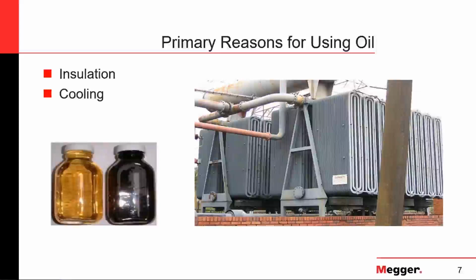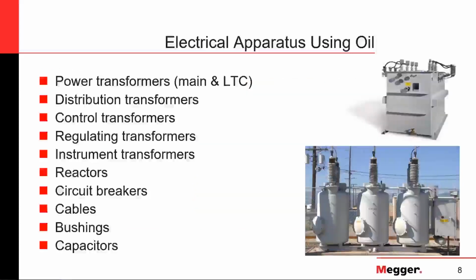Now this solid insulation is rated up to a certain operating temperature, and this operating temperature limit is basically defined during the design process of the transformer. If those operating temperature limits are not kept within the acceptable limits, then of course the insulating system in the transformer is going to start suffering degradation, and then it will eventually fail.